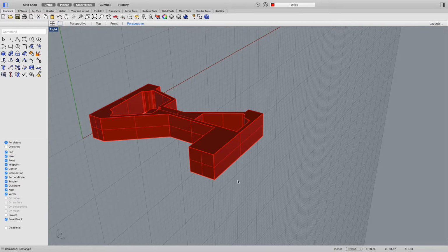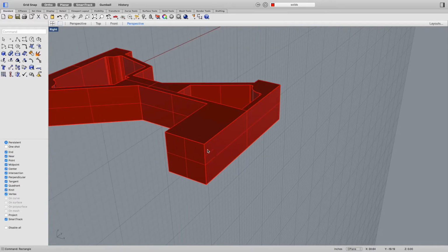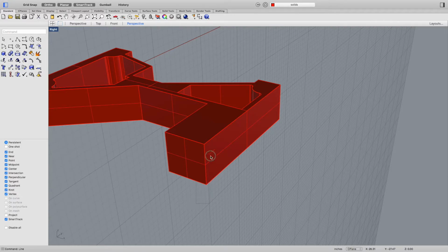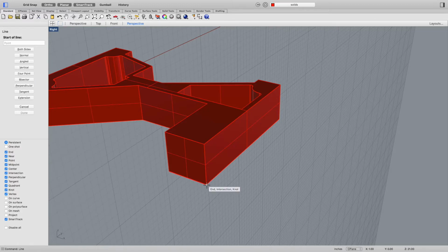So I'm going to draw on this edge here the cutout shape. So I'm going to go ahead and do a line tool down, and sometimes I go past it just to make it work. 1. Enter. Oh, it's not 1, sorry. Enter line tool. And make sure you grab that corner too. You could accidentally go to the wrong spot. I'm going to go 0.5. Okay, and then I'm going to do another one this way on this bottom here, 4 inches.